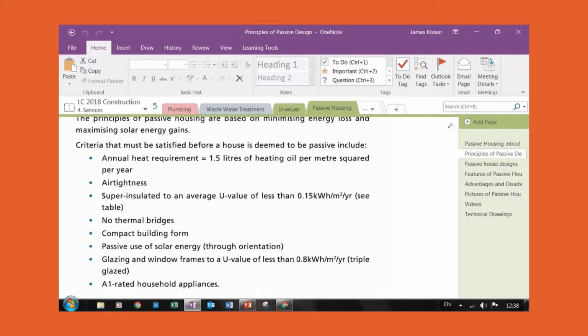But some people, it's kind of a traditional way of heating, still will want a passive house, but they'll still want to be able to burn something, even if it's just for the effect. What they'll have is, they'll put in this wood burning stove, but they have to bring in a pipe from outside to bring air in. Or else the other alternative is, in the depths of winter, you have to open a window for it to function. But if you're opening a window, it is no longer airtight.